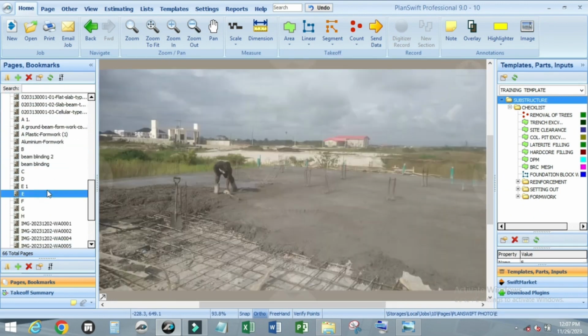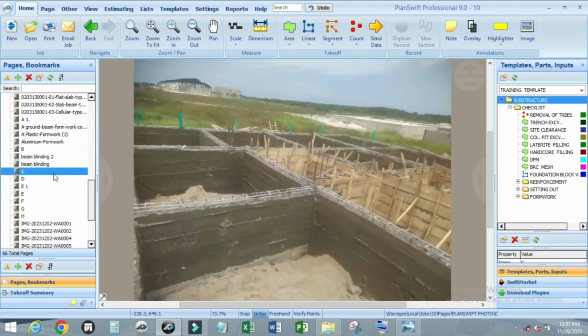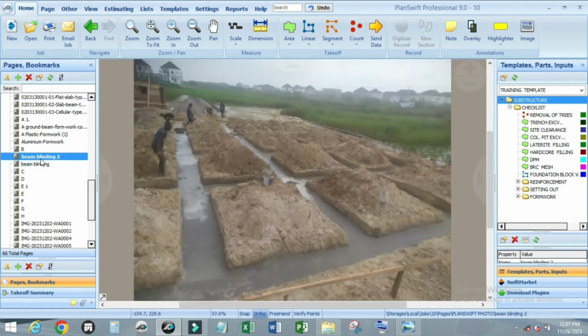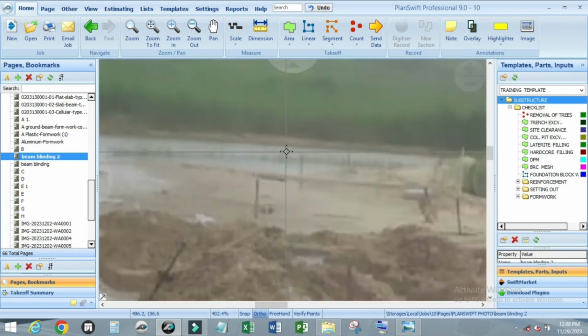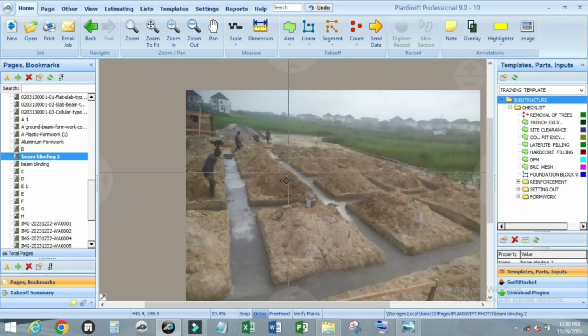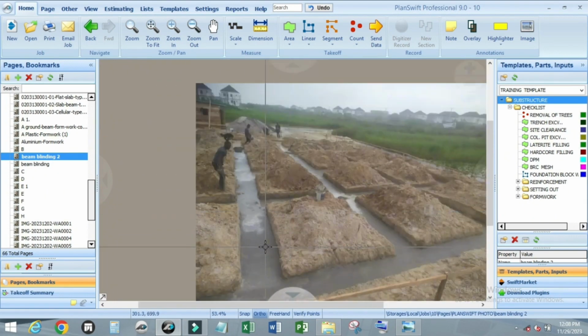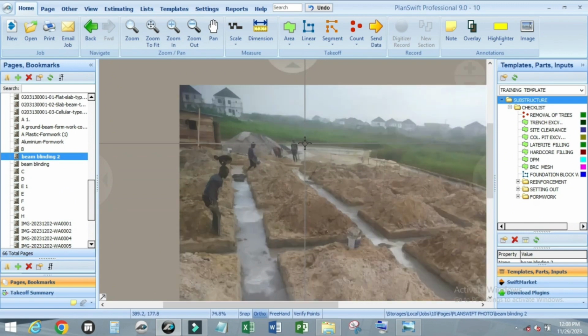Some of the sites are sand filled. They are sand filled. Can you see now? There's not much excavation here. All this area is sand filled. Can you see water here? They're sand filled, so no need to excavate much here. Once you set out, just use a shovel to pack all this setting out. After you have packed it out, you have to show the area that you're going to set out for each room or apartment. So it is a waterlogged area and it is sand filled.